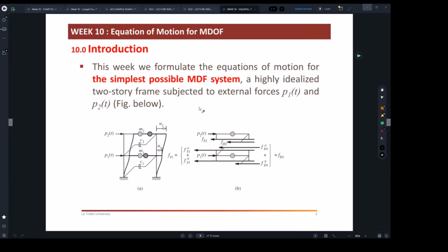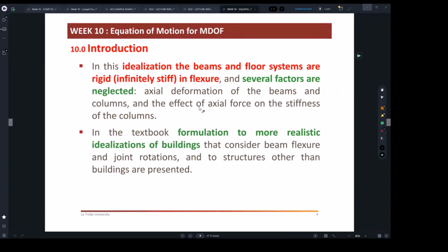Always in buildings, we're talking about, say, that 10-story building you design, usually the columns get squashed a bit. They get a little bit strained. We're talking here about a fraction of a millimeter, really small things. So in practice, we can ignore them for buildings, more like typical residential towers and buildings. But if we are designing something special, there are ways to consider them in your calculations because they're going to impact the vibrations and mode shapes a bit, right?